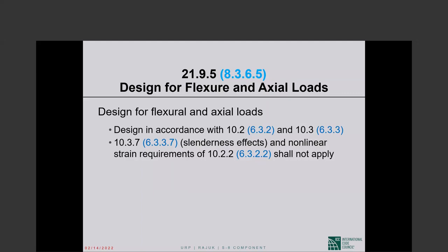And the infill actually used to get damaged in an earthquake. There was diagonal shear cracking leading to the failure of the infill, and the frame ended up doing the seismic resisting. But those days are long behind us. Shear walls, for a long, long time, have been monolithic concrete construction.